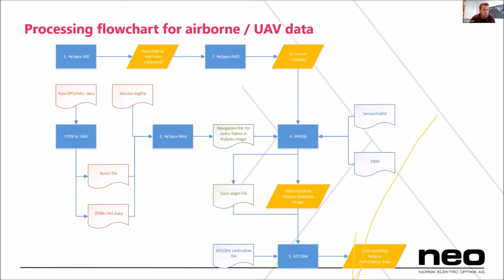Then to get really good results, you need to shift, since this pulse is synchronized with the beginning of each exposure. As Agnar also said, you have motion blur, right, because you're not exposing your detector for an infinitely short time. You're using a specific exposure time, and then the timing is shifted to the mid exposure. And that's done in HyperSpectral. And then HyperSpectral outputs one text file with XYZ, roll, pitch, heading for every frame in the hyperspectral image.